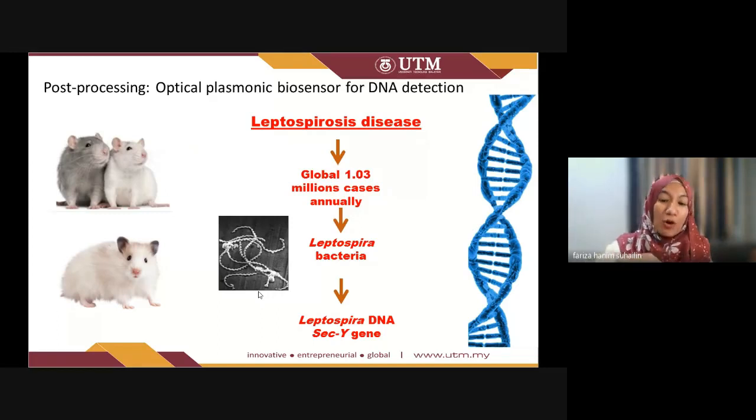We can polish the structures to give us D-shaped optical fibers, to give us tapered optical fibers, where because of these small optical fibers, all these changes will change the way the light is propagating, and then now we have evanescent fields that guide it at the interface of the fibers and also the surroundings.